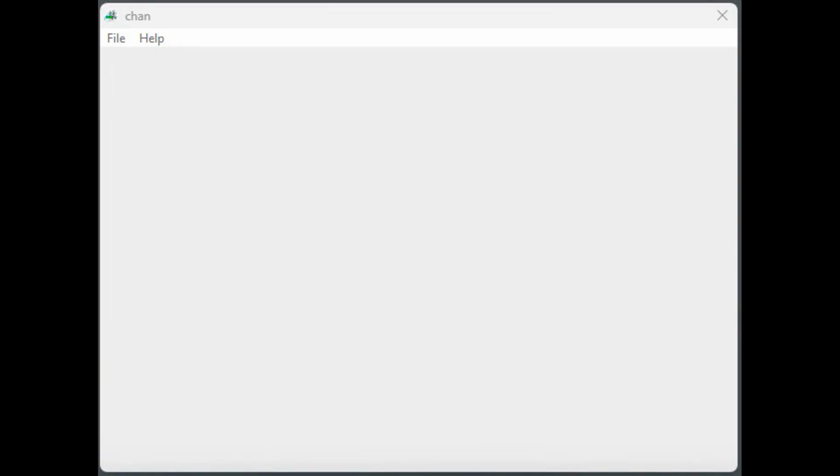Let's begin to explore the process for simulating a storm event and retrieving results. The first step is to define runtime controls. Select File from the main menu. Then click on the onepond.net file in the Recent Files list.